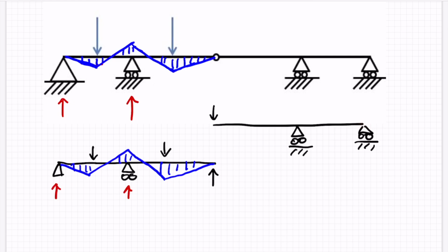So that means, first big clue, we do have a vertical reaction on the inner support, and it goes up. And now, if we resolve moments around this pin here, because we have an upwards force there, this has to be a downwards force here. There'll be different magnitudes because of the different lever arms around the pin, but the fact is there is still some kind of vertical force.